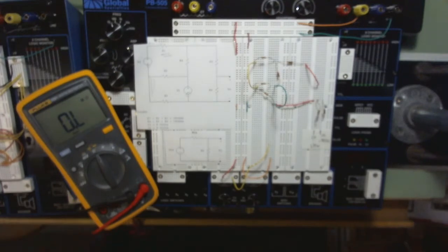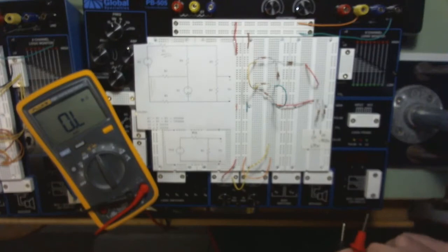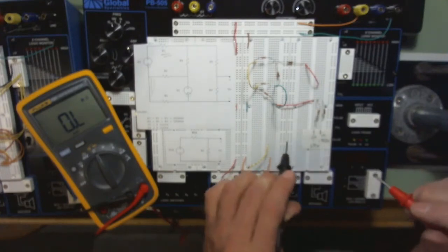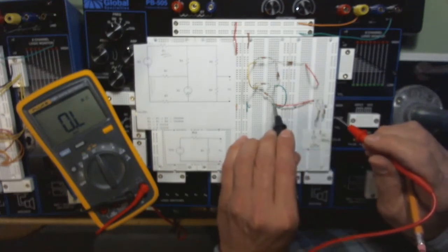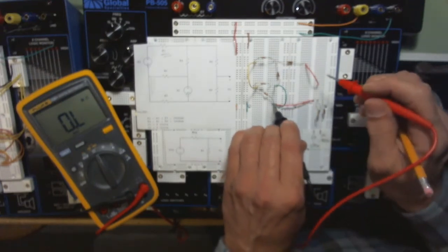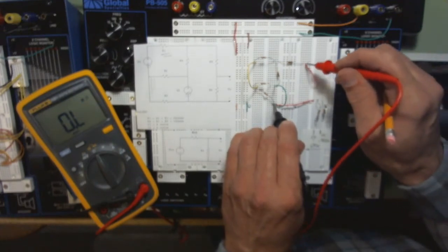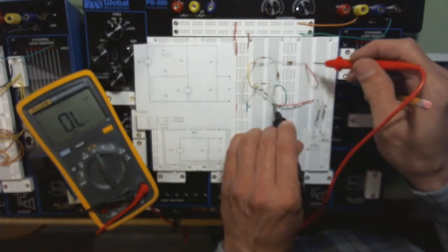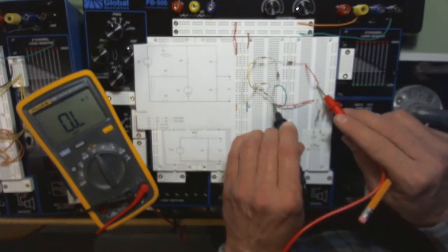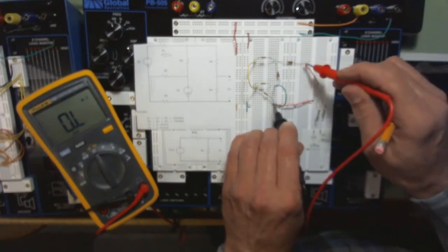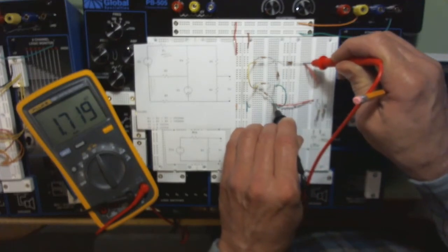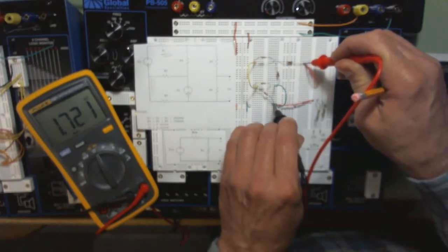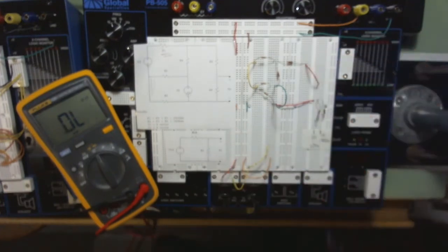Okay, 1.72. I'll check that again because that's a key piece of our experiment here. Maybe I'll run back over to here. So instead of measuring there, right there's a resistor. I can put the lead on, and instead of measuring here, I'm going to put it on there. That's just a matter of where these wires go in. It's hard to get contact, so I'll come back here where the lead is not insulated, and I can get contact better. 1.719, 1.72. I'll stick with that 1.72 k ohms. So good. We've got that.